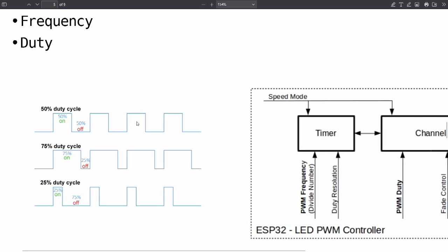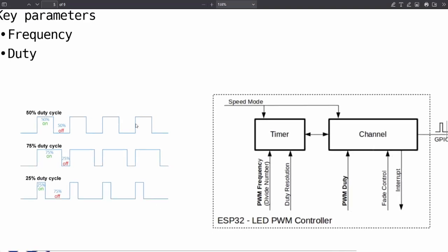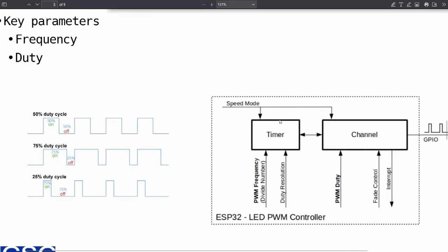The way that PWM is implemented, all microcontrollers have built-in timers in them. We can take advantage of these timers to be very fine-grained with how specific we need that duty cycle. Maybe we're controlling a robot arm and we need to move with micron accuracy, and we really need to make sure that it moves the exact same amount every time. Therefore, you wouldn't just want to write C code that sleeps for this amount of time and moves it for this amount of time. But let's look at what that kind of code would look like.